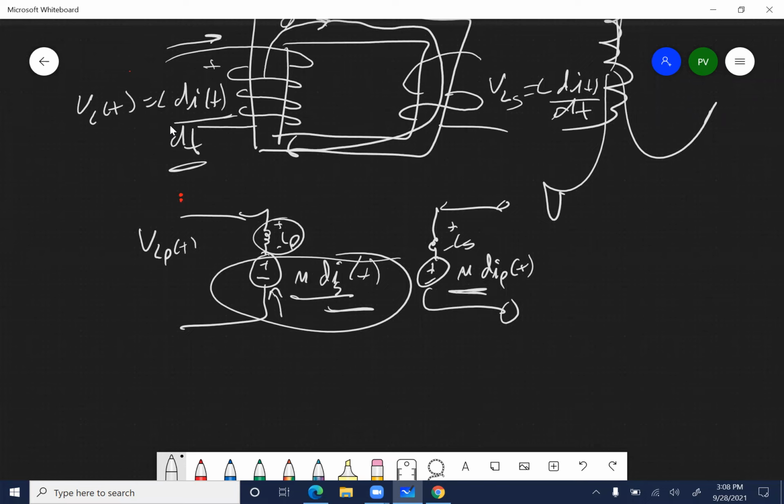So that's the nice thing about transformers in the real world. Transformers in the real world can go in either direction. I can take power and go from low voltage to high voltage, which is most of the time what generators do. The generator that's outside the window right now is probably running at 480, but you could step it up to transmit power all through campus at 4160. Or if for some reason it was connected to a motor, or you had to pump water for it somehow, and you had to go in the other direction, the transformer that it connects to could go in either direction. So no efficiency loss, no differences. Doesn't matter if you go up or down.